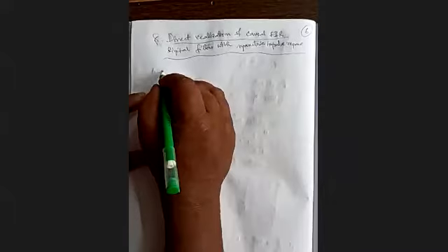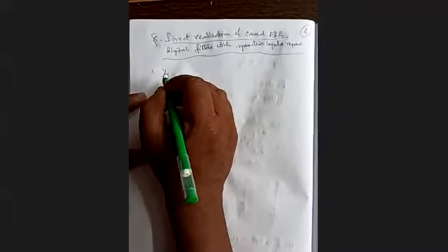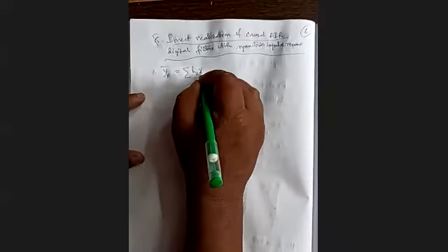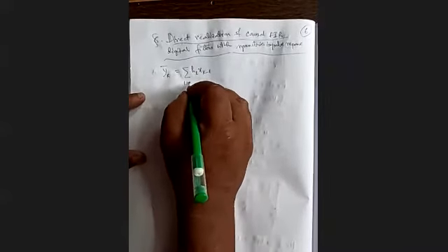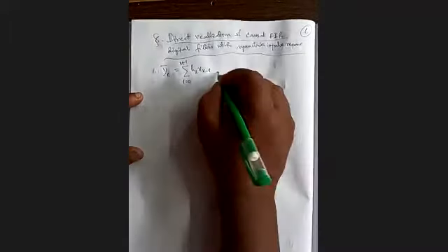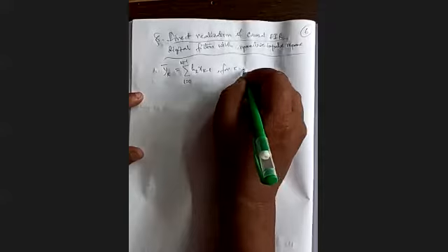Symmetric impulse response. Now the output is already known. It is y_k, y_k bar, equal to the summation of h_L x_{k-L}, L varying from 0 to M minus 1, for k equal to 0, 1, 2, and so on. So that is the usual relation.